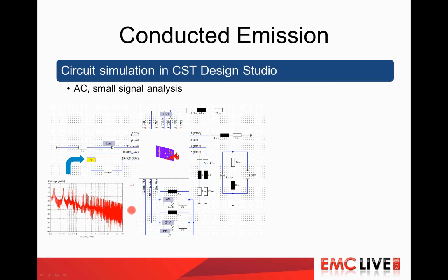Okay. Which PCB formats can be imported? So we offer a list of the most popular PCB tools. You can import from Cadence. We have a plugin for the Cadence environment. We have the possibility to import from Mentor. And what has been shown to be a very nice format for importing is the ODB++, which is a generic format which most tools can write. And if none of the formats is supported by your tools, we can also load a Gerber file. So there is always a way to get the data into Studio.